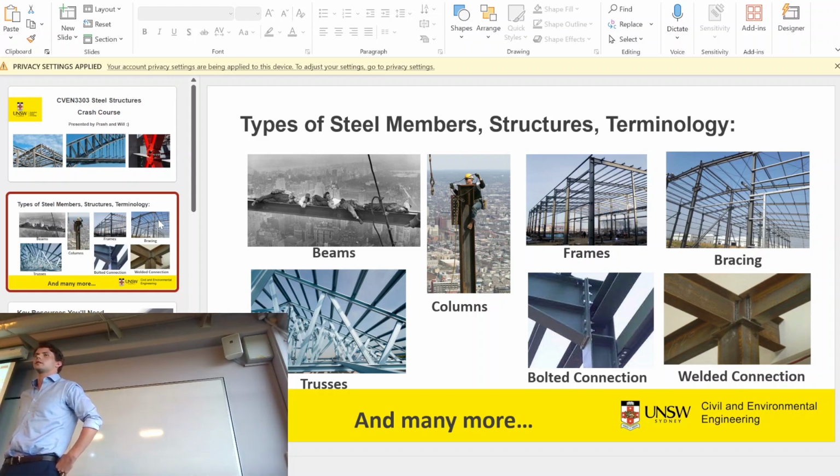To the other roll joint. Where is it on the floor? Yeah, on the floor, it has a roller joint, right? And then it'd be connected to a pin. And then multiple pins after that, right? So those pins, do they carry a moment? No. Good. So idealized, there's no moment throughout those structures, right? So they're purely tension and compression.